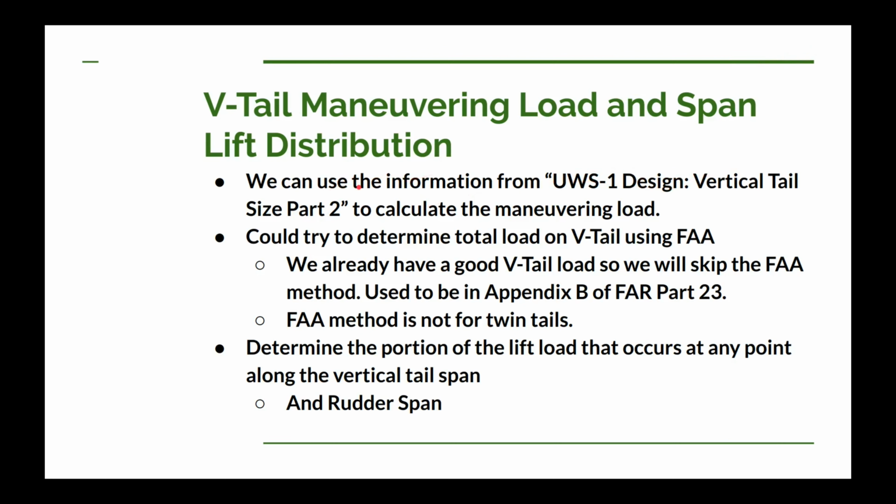Now, another way we could do it, well, not with the UWS-1, but another way that if you have a conventional configuration is you can use something from Appendix B of Federal Aviation Regulation Part 23. They had some nice charts and equations you could use to calculate vertical tail loads.